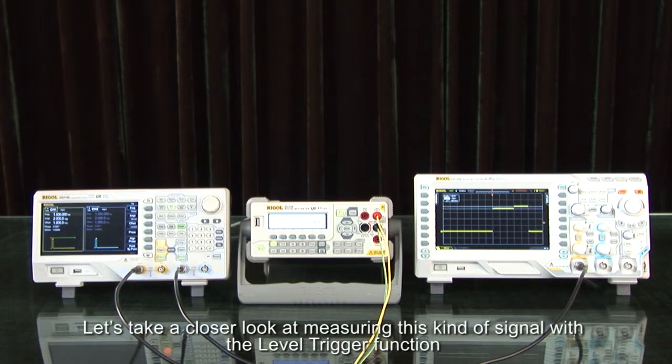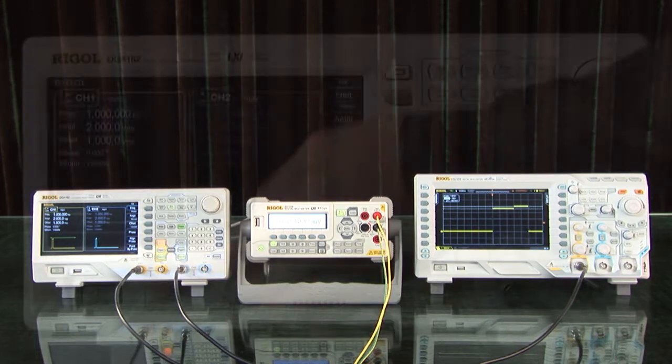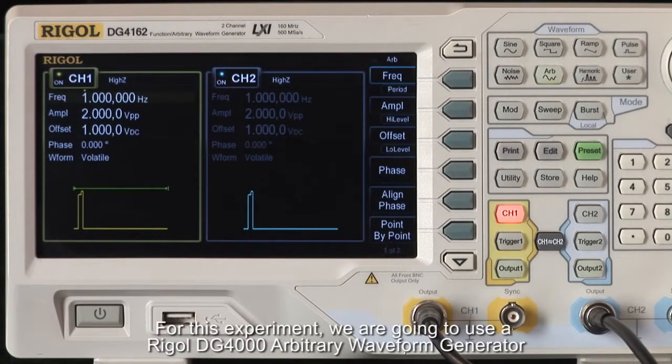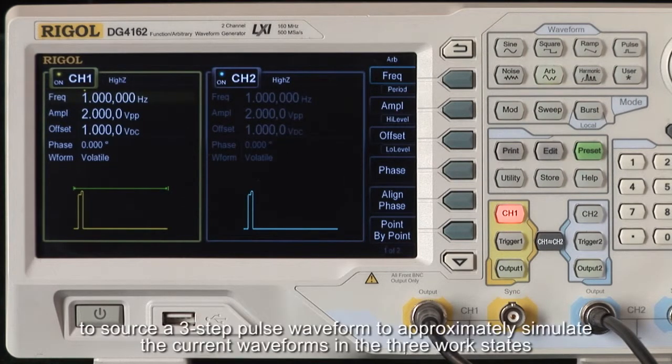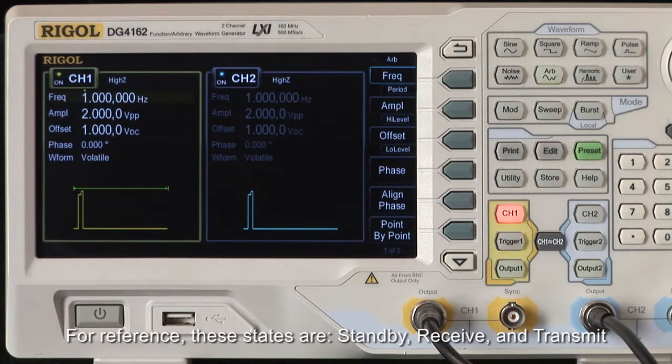Let's take a closer look at measuring this kind of signal with the level trigger function of the Rigol DM3068 digital multimeter. For this experiment, we are going to use a Rigol DG4000 arbitrary waveform generator to source a 3-step pulse waveform to approximately simulate the current waveforms in the 3 work states of a low power consumption device. For reference, these states are standby, receive, and transmit.